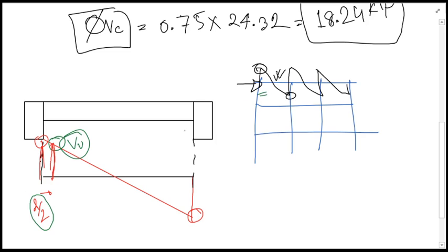After different combinations you might be getting this value as well, as we have got it for the flexural strength. We have drawn the tables, and similarly you will have to draw the tables here as well. In case of VU, you will not have to take the positive and negative values, rather the maximum absolute value, you will be taking for shear. That will be enough for us.